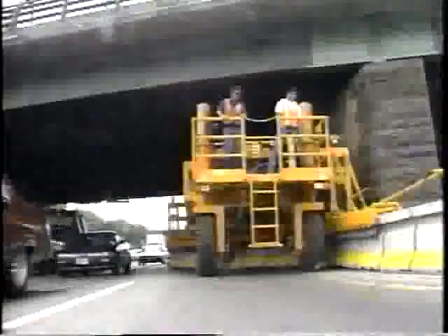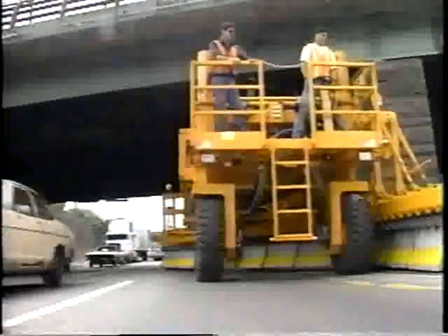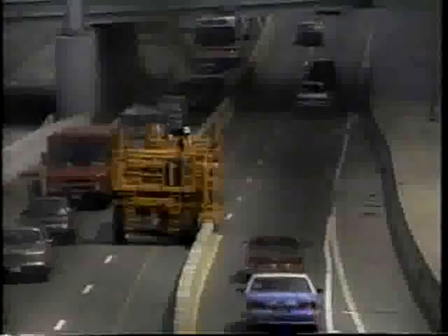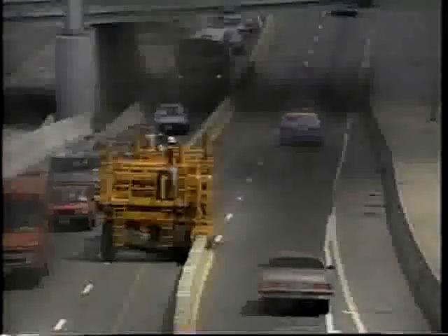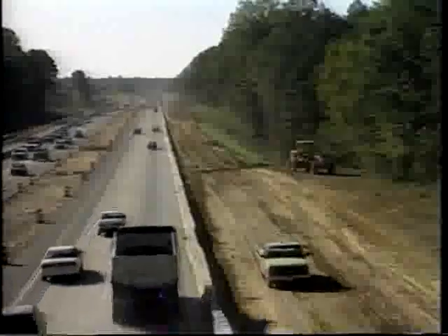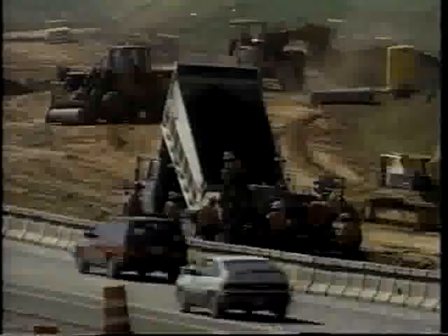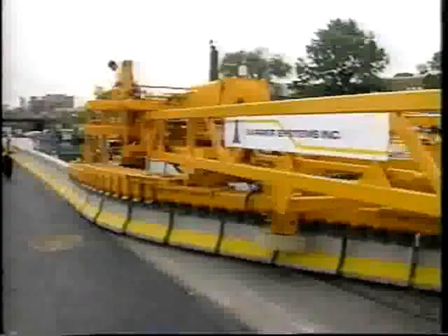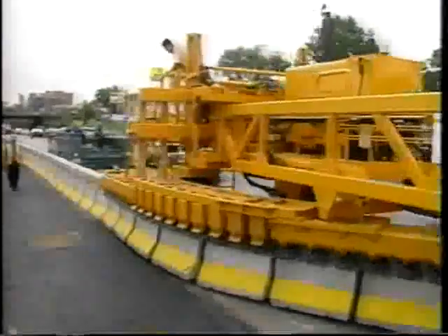Movable barriers are crash-tested barriers that can be quickly moved across the roadway in a continuous, safe operation. They should not interfere with or create additional hazards to traffic as they are being moved. Their two primary functions are to provide clear delineation of the newly created travelway and to provide positive separation of traffic from the work area or from other traffic. The ability to be quickly moved changes how and when barriers can be used.